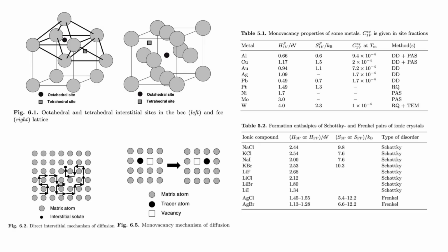Hand waving, we're saying, okay, because of entropy, right? So you create a vacant site, your configuration entropy is now non-zero, because you have two species instead of one species. So you have the gain in the configuration entropy. So we're going to be looking at that. But the overall idea is how much energy does it take to create a vacancy? Because the other penalty would be when you remove iron from the structure, you're actually going to cut bonds.